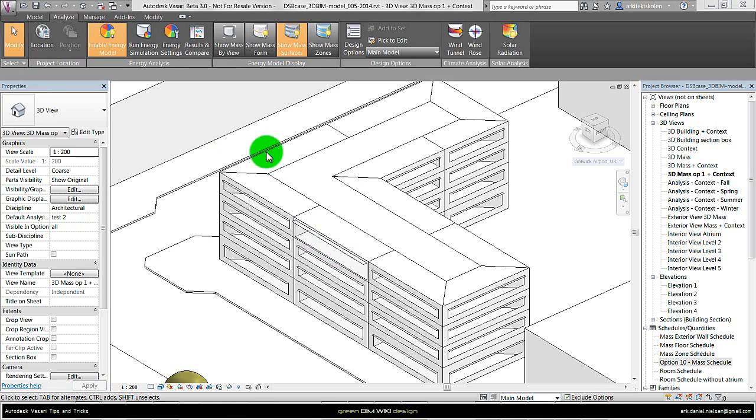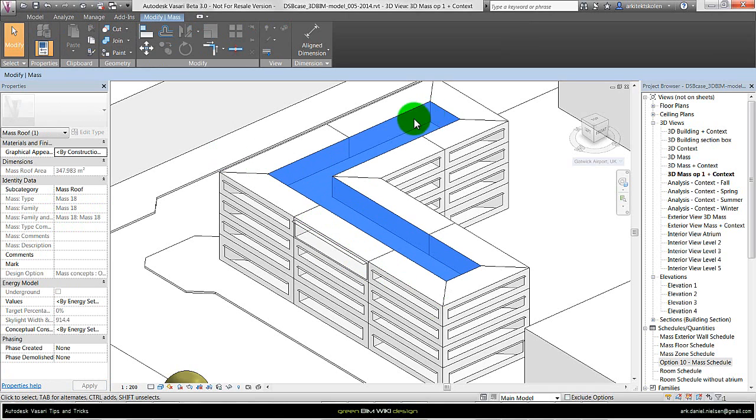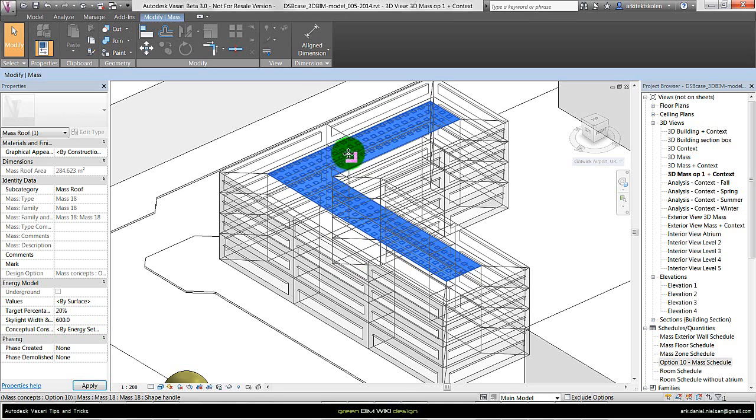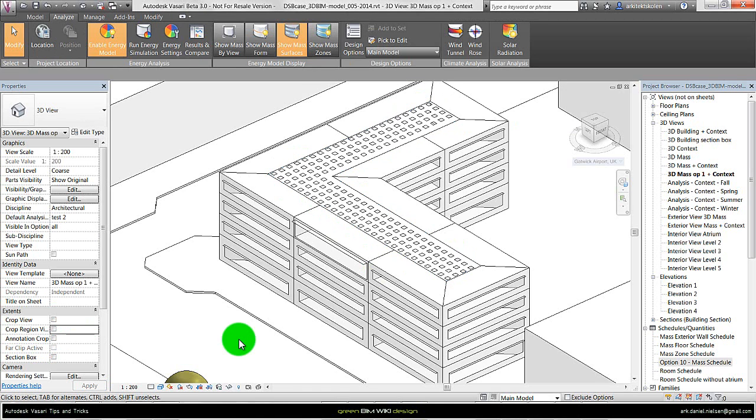than a wall. And just to show another example, let's say this room here also had skylights. This restroom zone is changed from energy settings to surface, saying alright, there's a percentage of skylights of 20%, and the size of the skylights is maybe 600 times 600, and then we see that it will create small openings all over this surface.